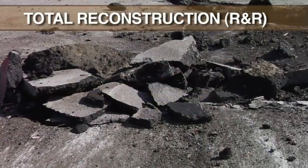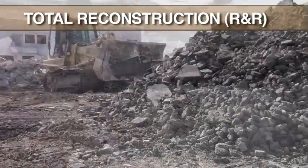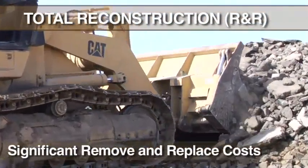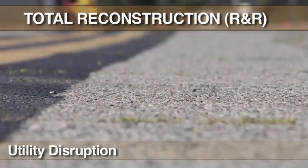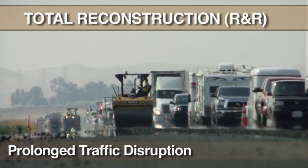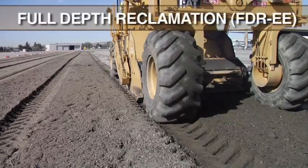However, a typical remove and replace project involves removing the current section and excavating additional materials to make room for the newly designed section. The cost to remove, transport, dump, and import new roadway materials can be extremely costly. This doesn't include the possible costs associated with disruption to existing utilities, as rerouting is often required. Nor does it include user costs due to the disruption of commercial and residential traffic because of the prolonged lane closures. An alternative option can be a full-depth reclamation.